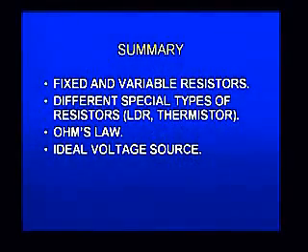I finally talked to you about an ideal voltage source. An ideal voltage source is characterized by zero resistance, and an actual voltage source will have small value of internal resistance. We should always be conscious about this fact that all practical power supplies and voltage sources will have finite though small resistance as part of its internal circuitry. Therefore, there is an internal resistance which is very small, which we have to take care of in the applications of different circuits.